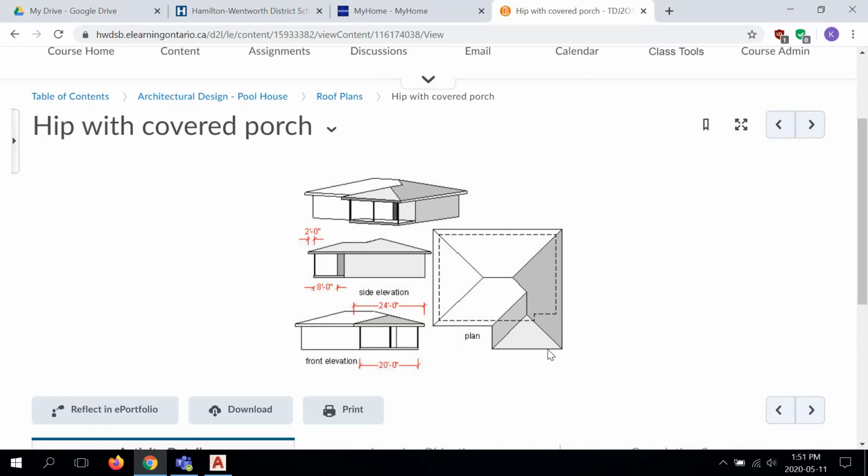As you can see here on top, your roof plane extends outward to cover that porch, right? Because this porch is not actually part of the floor plan. So this is typically something you could include on your pool house as well if you wanted to do this. And sometimes adding covered porches helps to simplify roofs that could be otherwise too complicated to solve or really hard or impossible to solve based on the floor plan layout.